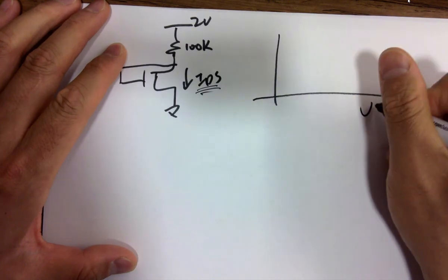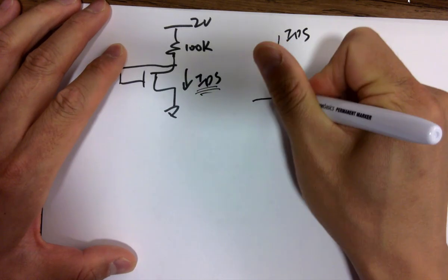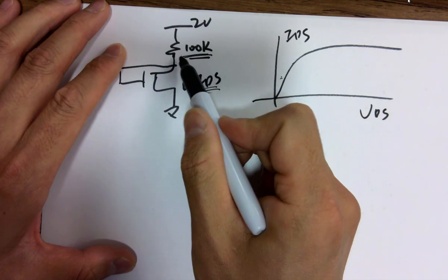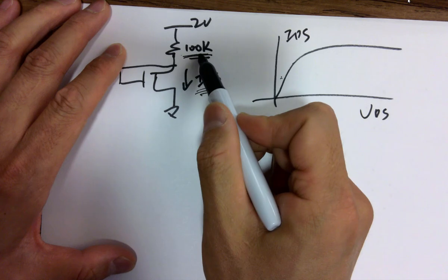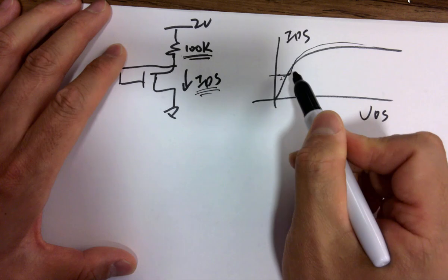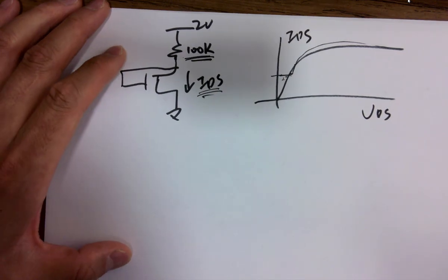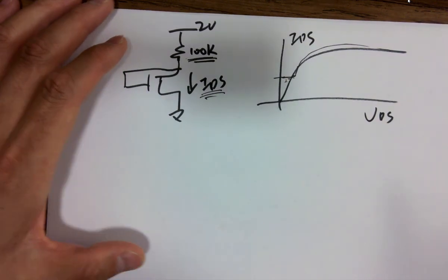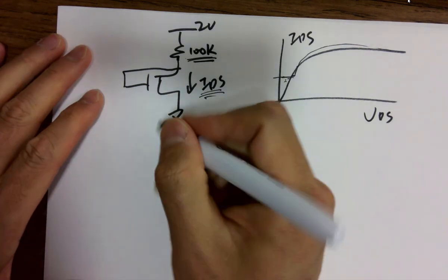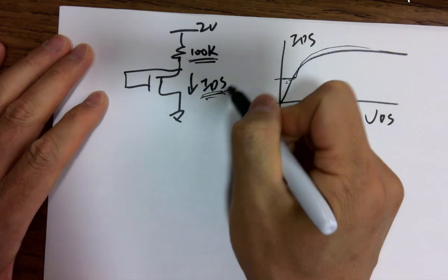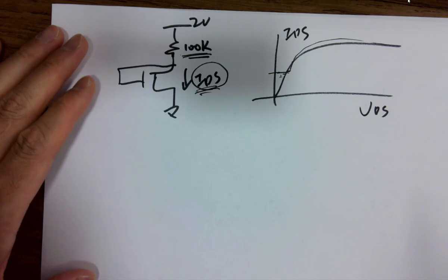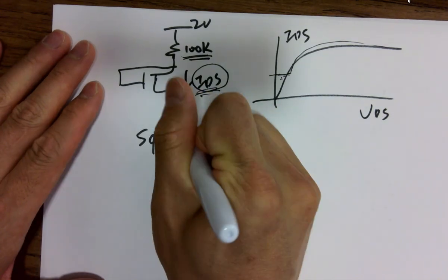If you look at this, VDS, IDS, right? And if the IDS is too small because the large resistance is limiting the current going through it, then it will have a lower current, so it is forced into the linear region. However, we can do calculations and see if that's the case. So how do we do a calculation for this? First we need to know how we represent the IDS in the NMOS transistor. There's an equation called a square law equation.